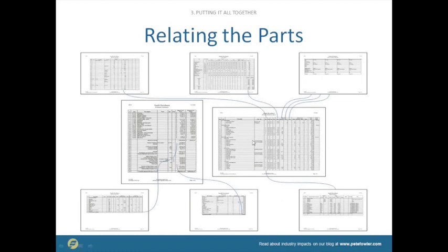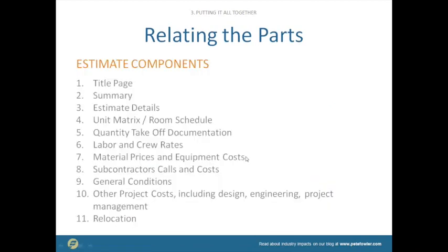So all of these details can be included on the estimate details page, but those estimate details then get summarized on the estimate summary. If we've got 3 man hours a window, how much does a man hour cost? Our assumption is that we're going to have a foreman, a laborer, and a journeyman carpenter. That's our crew, and all 3 of them put together cost whatever, $160 an hour, and so on. That's where that goes.